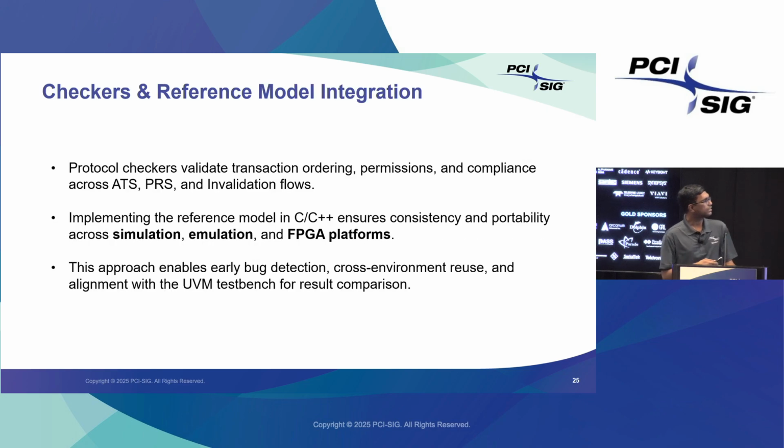Yeah, and the checkers. I think the important things we need to verify in the checkers: the basic UVC checker will tell whether it is following all the protocol rules or not, but our reference model needs to validate the ATS transaction ordering and the permission checks and compliances across these 3 flows.